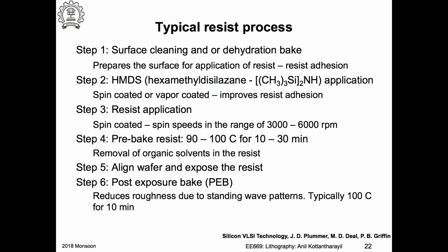Mask. So now you can use this photoresist as a mask, and the mask can be for wet etching, dry etching, and implantation. These are the typical processes, or for lift off, for example. And after that you remove the photoresist.